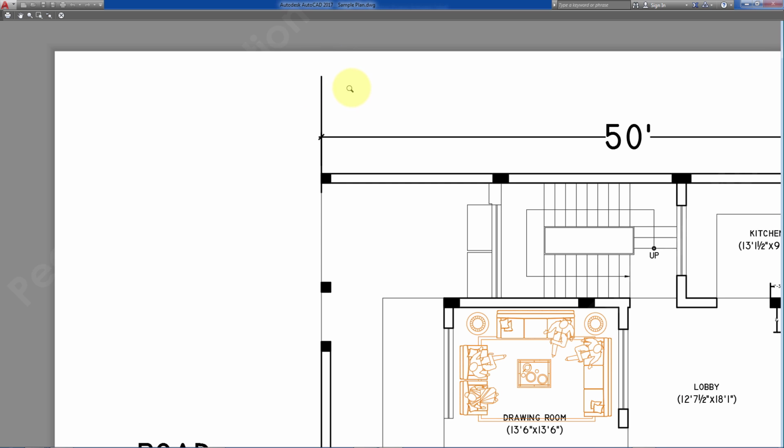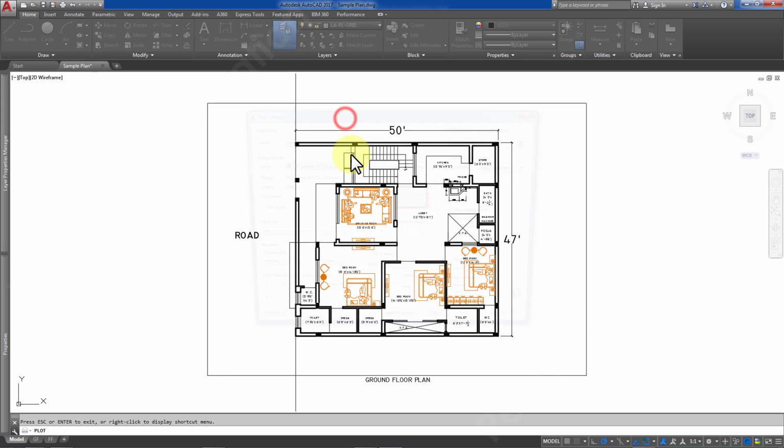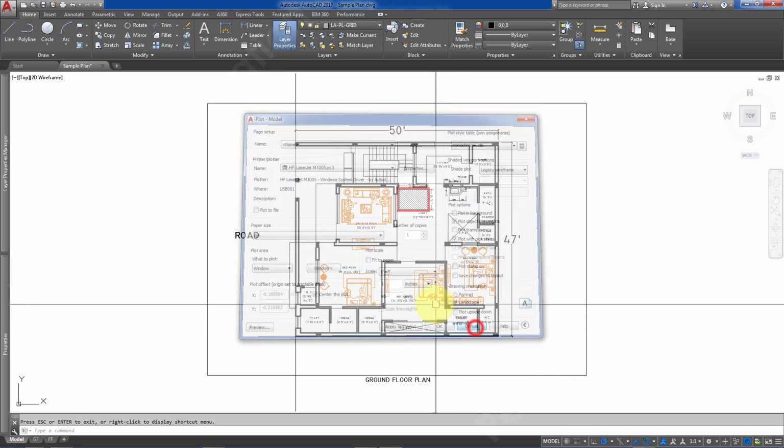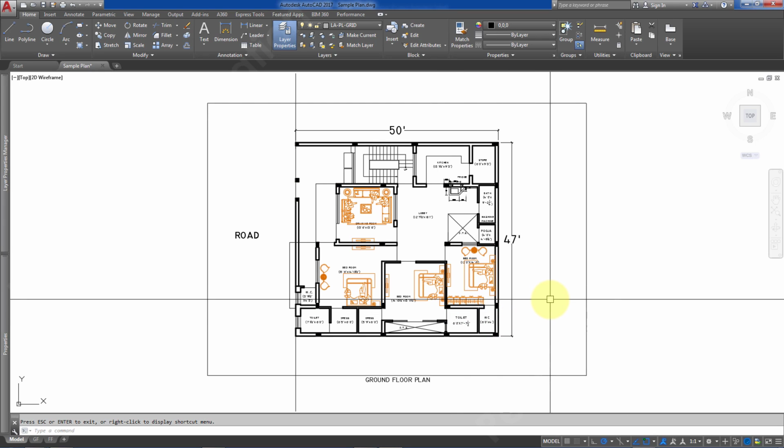Due to this, our drawing size gets reduced when we take the actual print on paper, and further the scale doesn't come accurate. That space around the corner is used by printers to grip the paper so that it can be rolled inside the cartridge for printing, which is the non-printable area by default. So to make your drawing scale more accurate, it's important to take that area also into account.